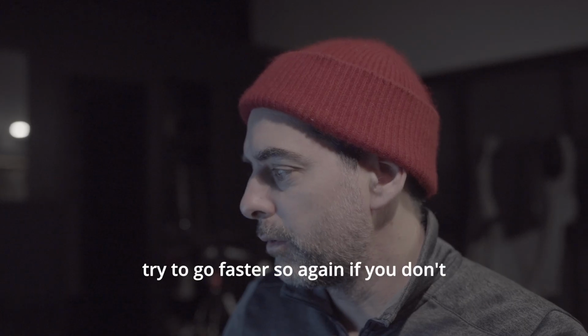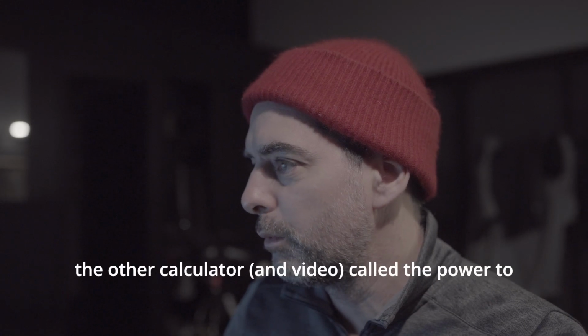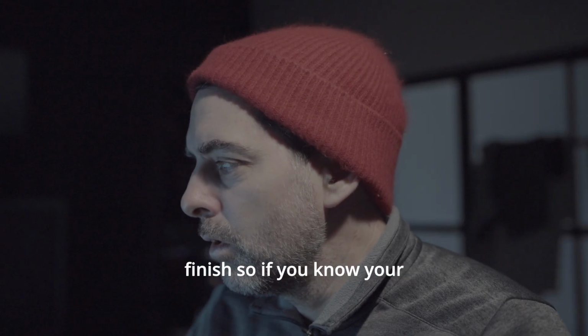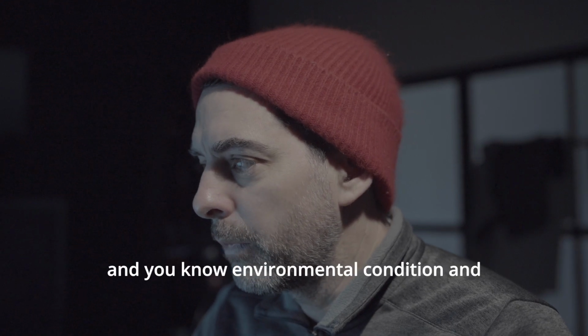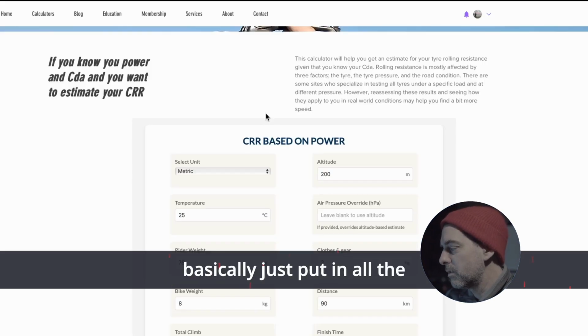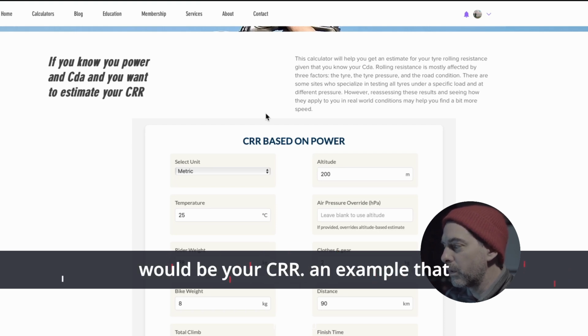So again, if you don't remember, I gave a bit more description of CDA and CR on the other calculator called the How to Finish. So if you know your CDA and you know your power and you know your environmental conditions and you're trying to look for your rolling resistance without having to use extensive equipment, then what you can do is basically just put in all the data that you have and look for the missing variable, which would be your CR.